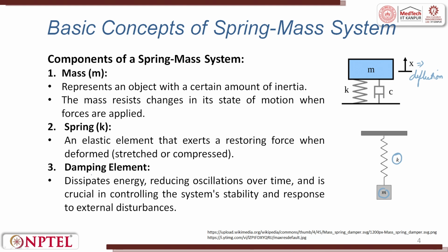The third element is the damping element. The damping element dissipates energy, reducing oscillation over time, and is crucial in controlling the system's stability and response to external disturbance. Okay. Damping is very, very important because once the spring is taking a load, the spring has to dissipate the energy such that it can bring the mass back to the original position.